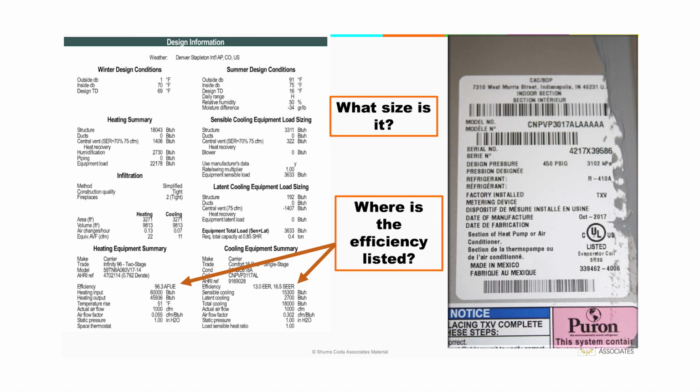And the insulator comes in and says, we don't do R27, we do R30. And then it changes again on the fly. Well, and here's the deal. If it's a wall, don't get me wrong, a wall has an impact on heating and cooling loads. It's not the highest impact on heating and cooling loads. If they had to change out the ceiling or the windows, oh heck yeah, then there's going to be a different discussion. A couple of R values in a wall is not going to make a big enough difference typically that the equipment's going to be oversized. If it is, I'm going to say it's oversized by 10 BTUs type of deal.